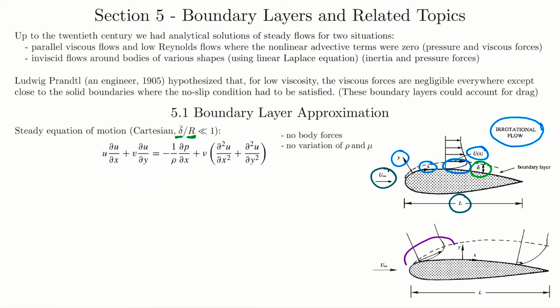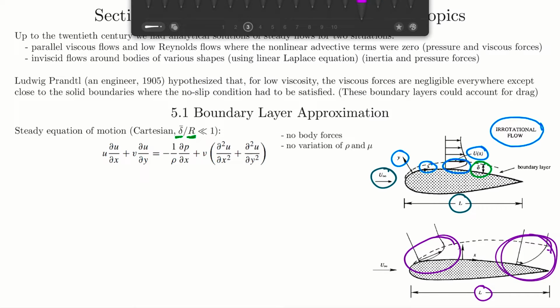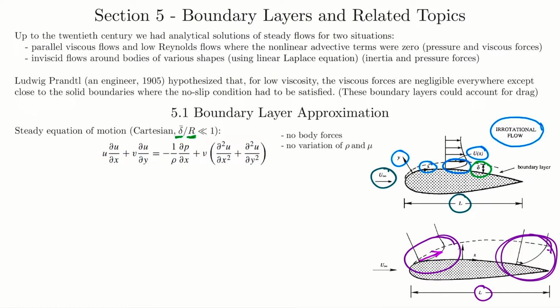So we can look down here now. If you have this velocity profile here, and then along this distance L we have this second profile down here, you can see that the velocity within the boundary layer at a certain distance away from the surface, shown with these arrows here, I'll trace over them as well, this arrow here and down here this arrow here, has changed by approximately the scale of u infinity over this distance L, right? So that will serve as our good scaling distance, capital L there.